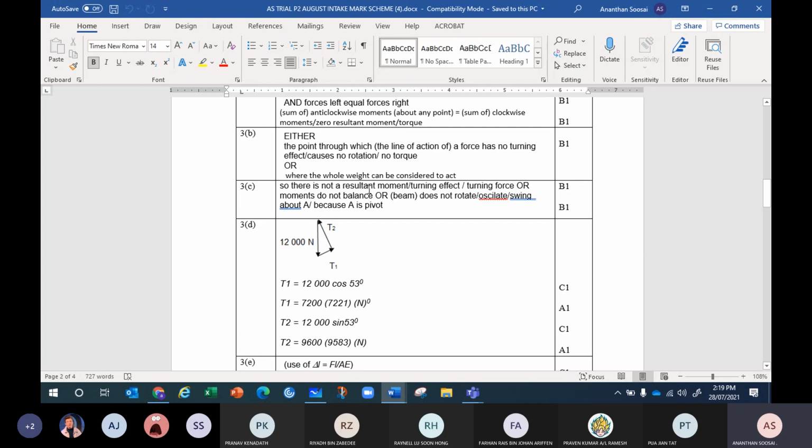Okay. Riyad, do you have the idea? Yeah, sir. Thanks. So always go to the two conditions to be in equilibrium. Resting, net force is always 0, but the resultant moment also must be 0. To have no resultant moment, the force should not have a perpendicular distance from the pivot. Only achieved when the CG is below the pivot vertically.